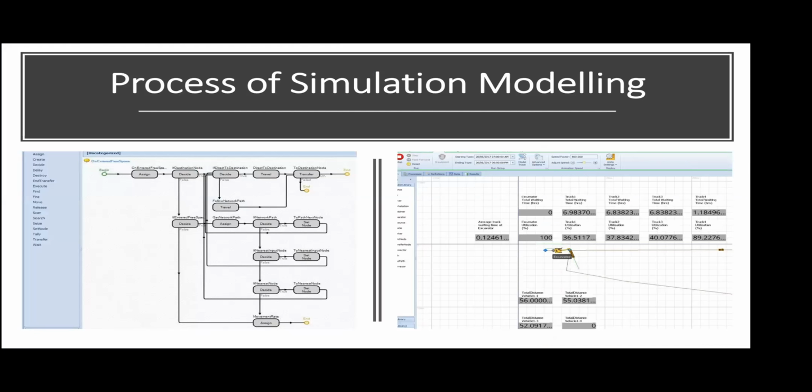So this is how the back end of a simulation model looks like. This is Simio, a software called Simio, which I used during my PhD. We created a simulation model for earthworks. So we were digging. This is on the site of A556. We are not using the pictures of the road itself, so you can only see the numbers and the excavator. The excavator has a lot of dump trucks standing in front of it. So we were doing quite a lot of cut and dig operations. We were cutting soil from one point, taking it, and dumping it somewhere else so that we can have a straight road at the end.